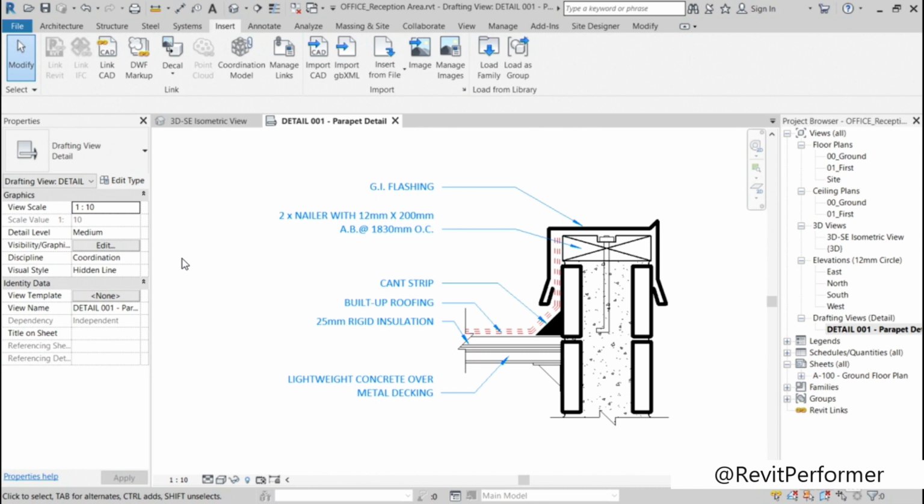And the benefit you've got there as well is it highlights everything in the detail, but also think about your standards coming in from your AutoCAD drawings as well. So you might be linking some AutoCAD drawings into Revit, and you want that text to be highlighted in a particular color. You can highlight any text in a linked or imported CAD drawing as well. Just use your visibility graphic overrides to do so. I know we're doing it here in a detail that is already Revit objects and Revit annotation, but can you see the crossover there?